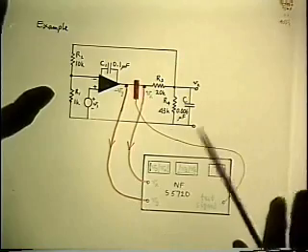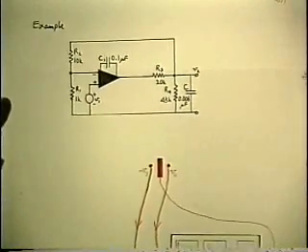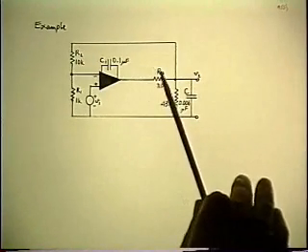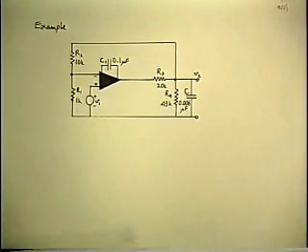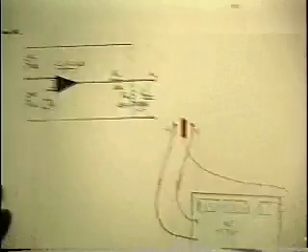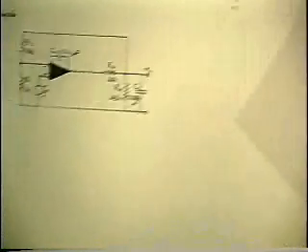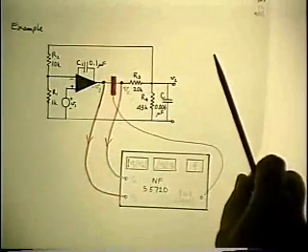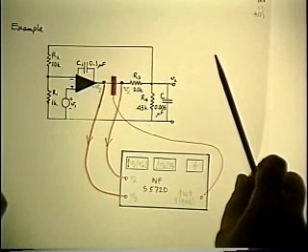And what you do in practice is you build your breadboard, closed loop, you turn on the power supply and it comes up and it runs, and you have this test instrumentation sitting on a cart somewhere. Your circuit is already up and running, and all you do is wheel up your cart full of equipment and hang on 3 probes while it's running. You don't even have to turn it off to do that.